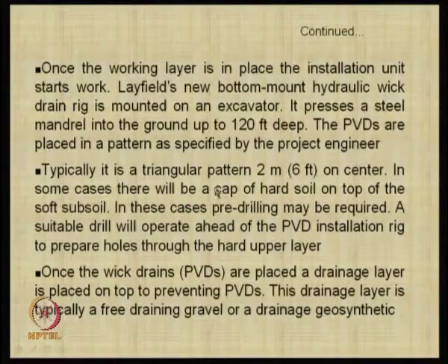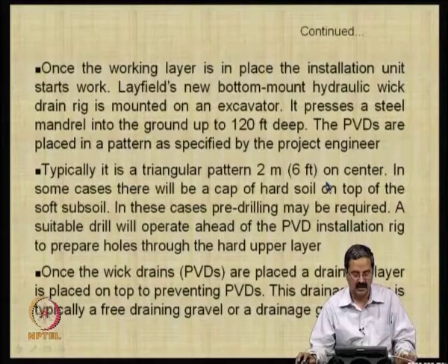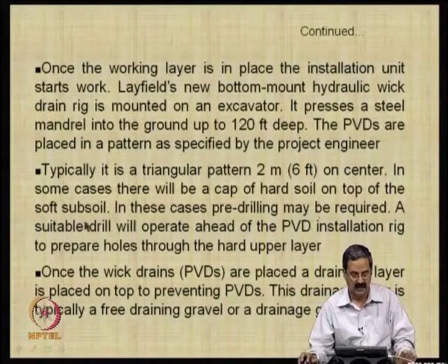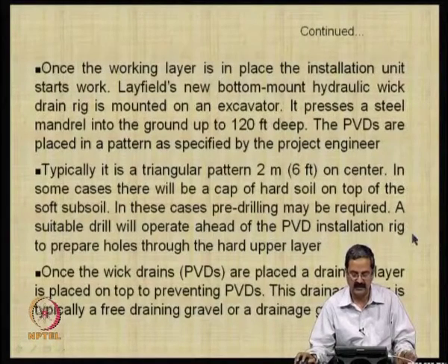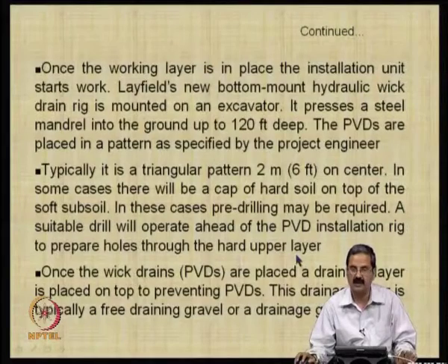Now, you have some of the equipment like the mandrel, we have seen that it can go up to long depths, and it can be a triangular pattern, and there are different types of drilling actually, like we will just see that, and a suitable rig will operate ahead of the PVD installation to prepare holes through the hard upper layers.